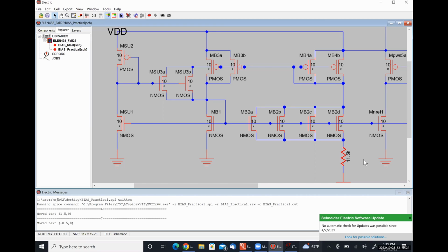What did you say? I was asking what they were talking about, the mention of annotation text, and I'm using annotation text. Okay, so let me show you. I did things slightly differently here than we did on the other ones. Click on any of your transistors. With that one selected, press Control I. Give it a name there. That way, that name is what it has inside LTspice as well.